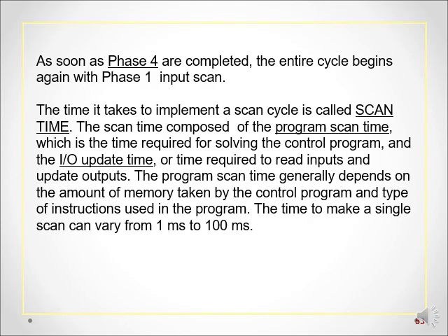So you have to understand the scan time, based on how fast you want your PLC to run. The time to take a single scan may vary from 1 millisecond to 100 milliseconds. This is an old note. Maybe nowadays you may have less than 1 millisecond as well.